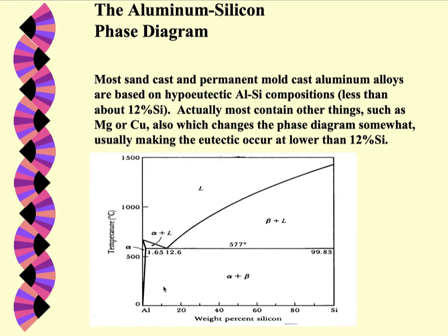So if we have a 6% or something like that, this is 10. So we have a 6% alloy. We would heat up here. It would first start forming liquid, and then it would be completely liquid. And then as we cooled, it would come back down. So you really can't change the composition of that metal so much. You go up and down on a single line, okay?